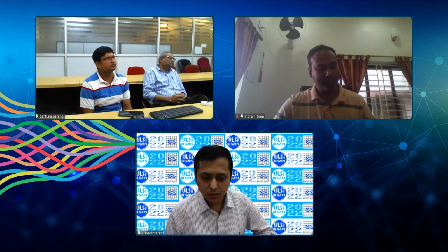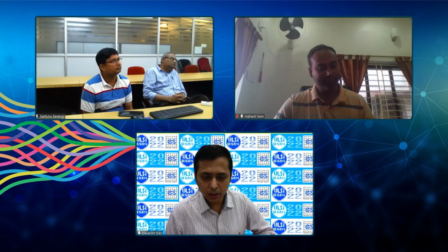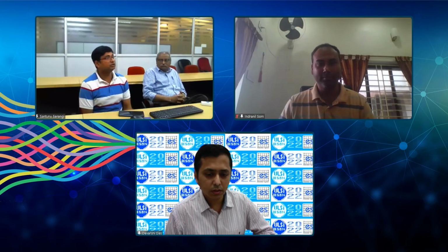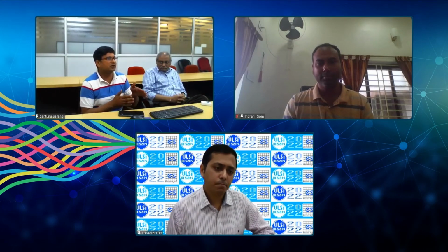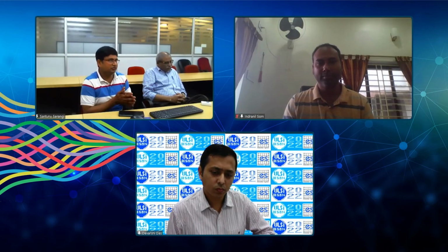Moving to the next question. In the proposed design, will the circuit only measure relative jitter between subsampled clock and the input data? No, it purely measures the data and it also purely measures the clock. For that, we are giving a sub-multiple of the external clock, so that will scan the data or clock transition region. There will not be any correlation between the data or clock with this sub-multiple clock. So it purely measures the actual jitter. It does not measure the relative jitter like others.